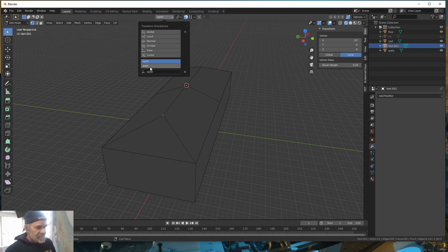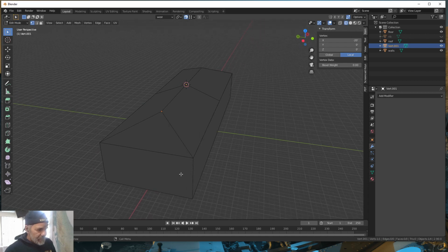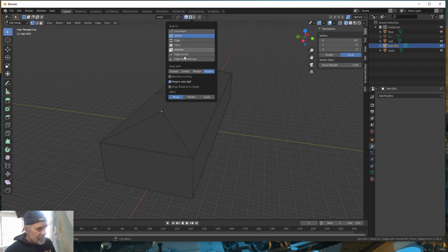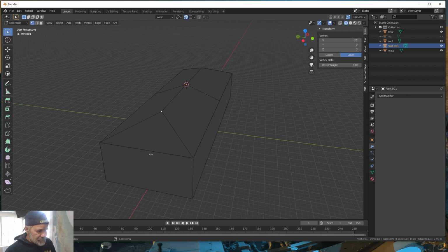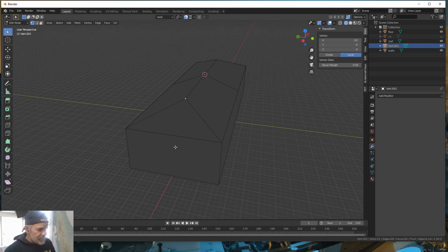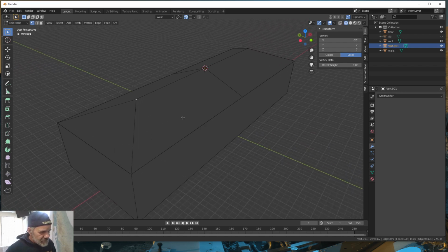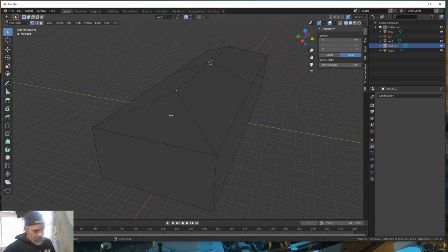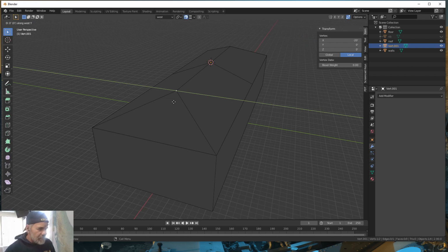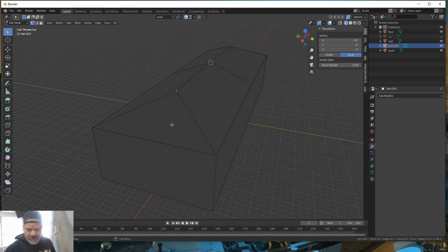So let's change our face to the west and select our vertice and go to edge snap, because there's no vertice down here, there's just an edge. So I've got edge snap, and I'm going to zoom in here, and we're going to extrude that in the X direction. Whoops, no we're not. Is that the X direction? That might be the Y direction now. We're going to, let me control that. All right, so we're going to extrude Y. Y is going that way. All right, I've got another thing I need to figure out.